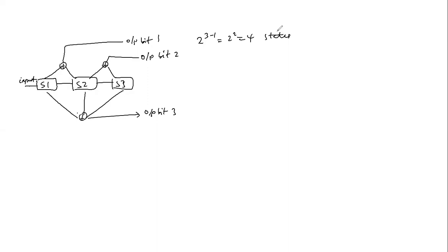But how are we going to map these 4 states among 16 possible code words? When we had just 8 code words, at least we know each state could transmit a 0 or 1. Same thing here. Each state will be able to emit either a 0 or 1.